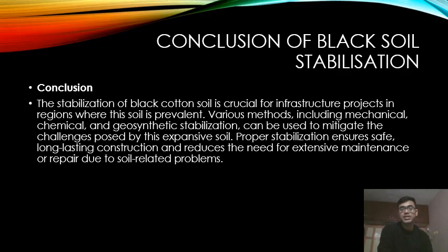So the conclusion is that the stabilization of black cotton soil is crucial for infrastructure projects in the regions where the soil is prevalent. No other soil is available where we have to construct, so on that black cotton soil, in those cases, we need to do the stabilization before construction. So black cotton soil stabilization is very important. Various methods including mechanical, chemical, and geosynthetic stabilization can be used to mitigate the challenges posed by the expansive soil. Proper stabilization ensures safe, long-lasting construction and reduces the need for extensive maintenance or repair due to soil-related problems.